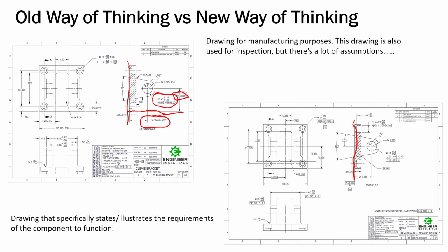If we come back over here, we have a position. It's composite position, but it's back to A and B. Now that is to the bottom and to these 4 holes. So that's directly relating back to the function of the part. But we also opened up the tolerances substantially. We've got 20 thousandths for location here back to the datum reference frame. Over here, like I said, from the bottom we're plus or minus 3.5 up, and from the bottom rail here we're up 3.5 thousandths as well.